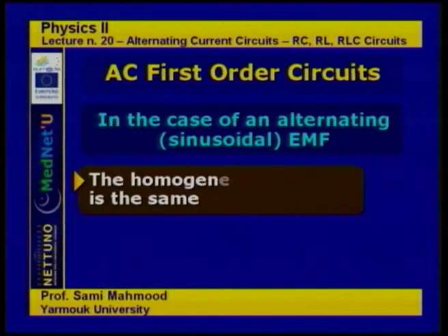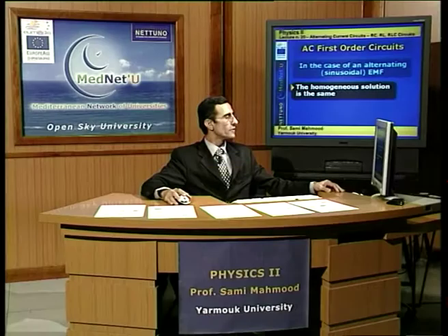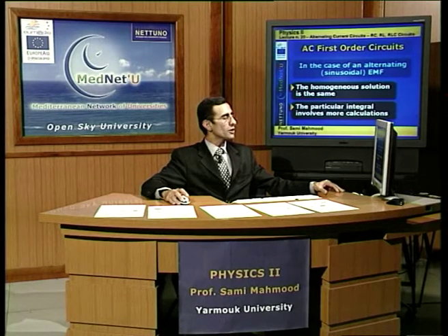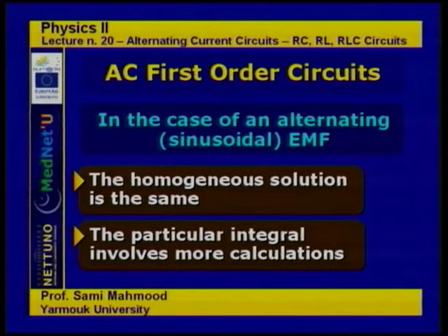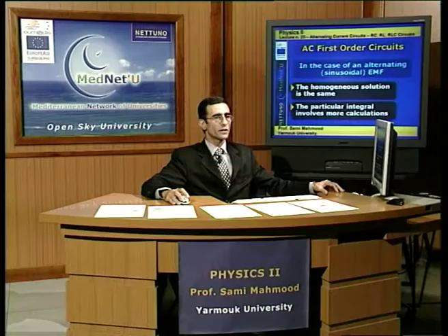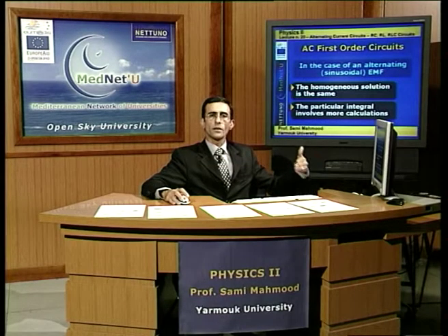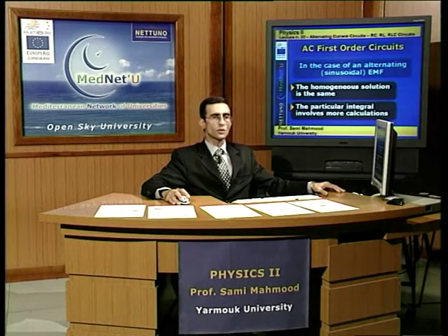But in the case of an alternating sinusoidal electromotive force, we remember that the homogeneous solution stays the same, which is the transient solution, because the transient solution is the solution of the homogeneous differential equation where the source is removed from the equation. And now only the particular part which involves the source is the one that will involve some more calculation. Integration and integral methodology is needed to do the solution.